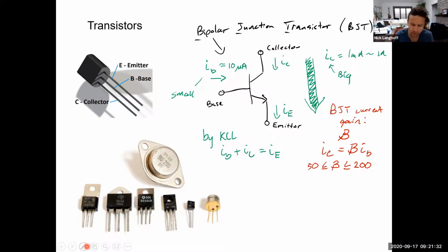So the bipolar junction transistor, or BJT, amplifies a small current going into the base, a little bit of trickle current, 10 microamps or something, not very much, and it can turn that into a much bigger current. What is that useful for? Well, if you wanted to create an amplifier that takes a really small signal out of a microphone and then drives a really big signal out of a speaker, and that speaker is moving much more energy because it's a much larger mechanical device, you need something to amplify the power on the way.